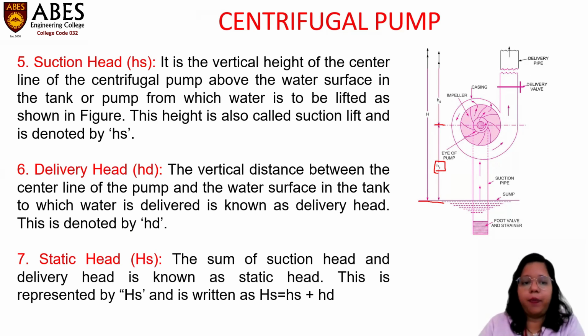Then delivery head. The vertical distance between the center line of the pump and the water surface in the tank to which water is delivered is known as delivery head. This is denoted by Hd.